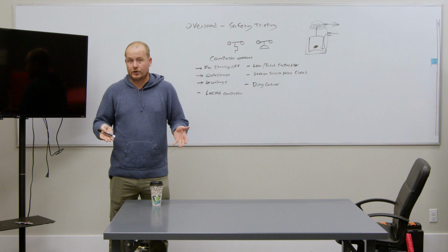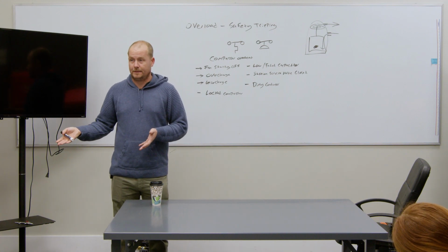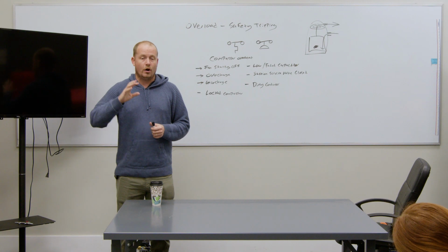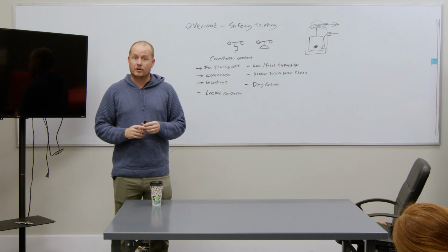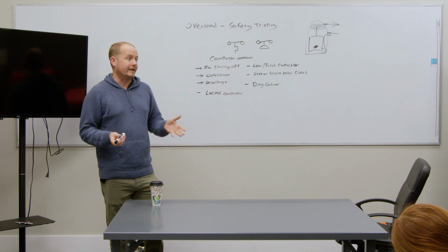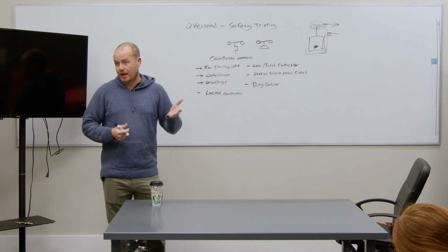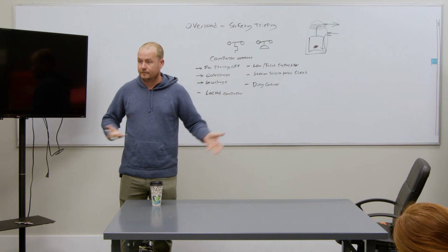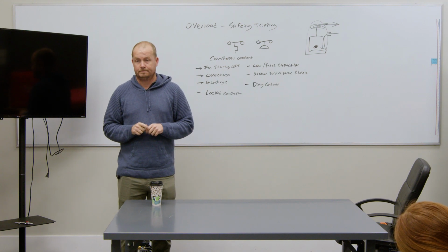You could have a case where your compressor is drawing lower than normal current and still overheating over time. And that's the difference between overheating because of an electrical problem, like we talked about, overheating in the motor, versus it overheating because it's not being cooled properly. In the case of low suction pressure, low mass flow rate, it's just not being cooled properly. You don't have enough stuff moving across that compressor and across that motor to keep it cool.